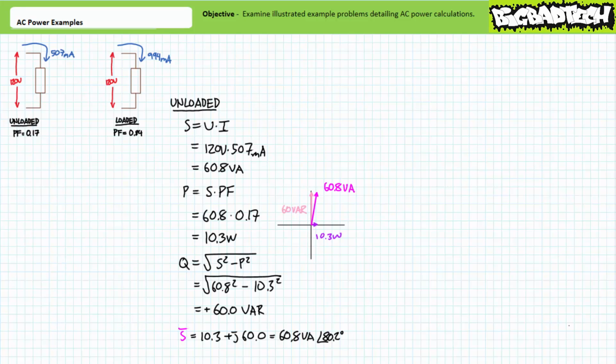As we anticipated, real power in the unloaded condition is relatively small, meaning only a small portion of power the motor is apparently consuming is being directed towards actual work, and a vast majority of it will be directed towards a reactive interchange characteristic of primarily inductive elements like motor windings. Let's solve for reactive power using one of our previously derived methods. Reactive power Q equals the square root of the differences of the squares of apparent power S and real power P. Substituting our given values yields a reactive power of roughly 60 volt amperes.